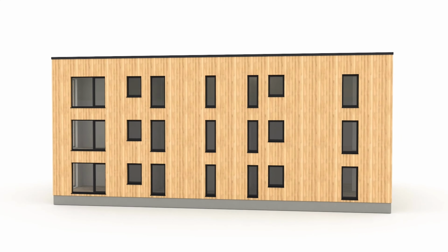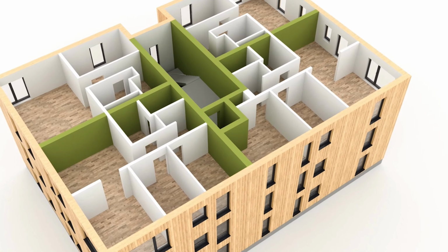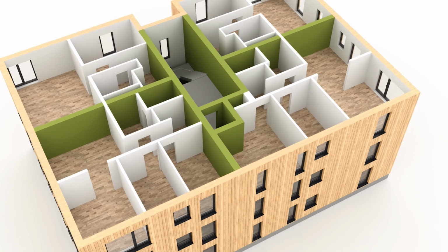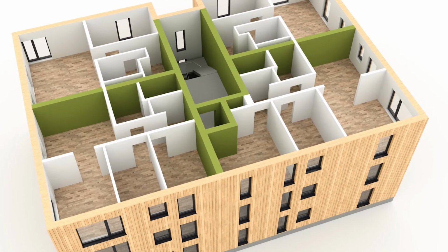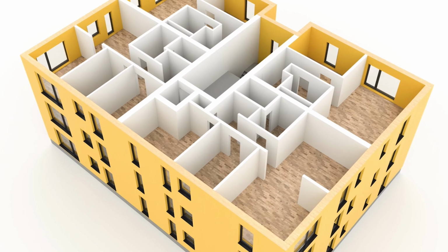Internal walls can be load-bearing walls, meaning that they provide essential support to the building, distributing the weight from the roof and upper floors down to the foundation. Some internal walls are non-load-bearing walls that create separate rooms and areas within a building, separating two rooms or an entrance hall and a bathroom. Exterior walls are mainly load-bearing walls that protect the interior from weather elements, such as rain, wind, and temperature extremes.